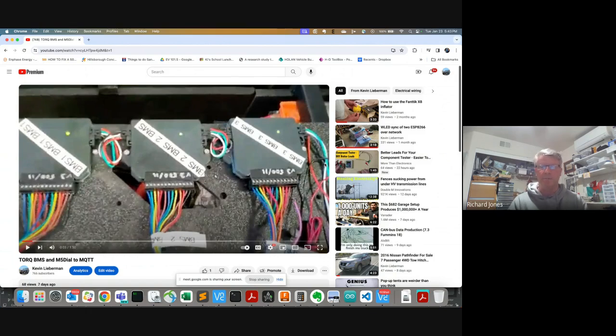But essentially, at some point, they both give you state of charge, or they give you the cell voltages. The Orion is definitely a high-end BMS that does lots of very cool things. It's also a lot more expensive, and it's sort of a central system. And the dilithium is sort of like a modern version of these Zivas. These Zivas are kind of neat, but unfortunately, they're not available anymore.